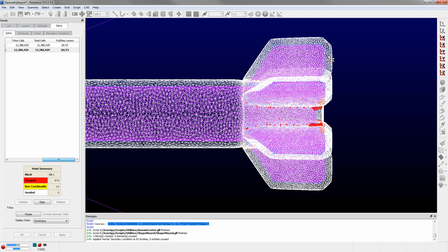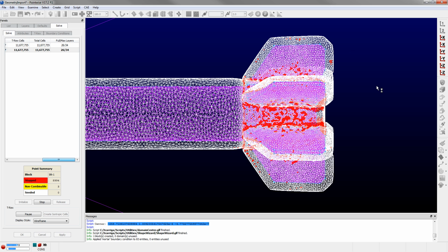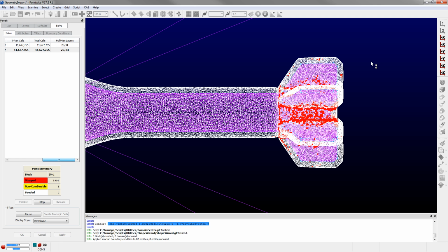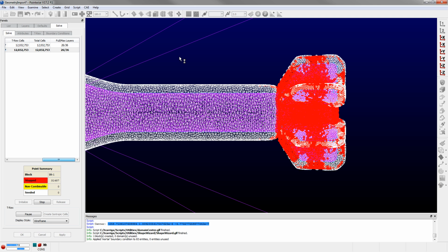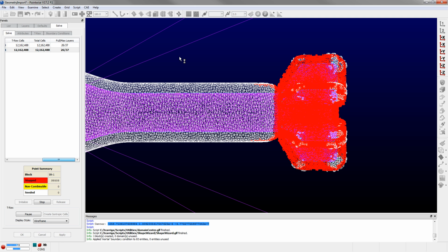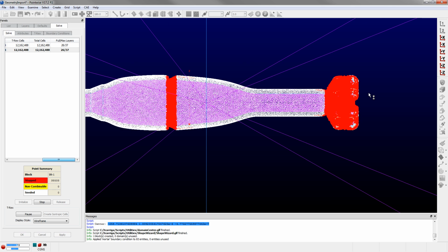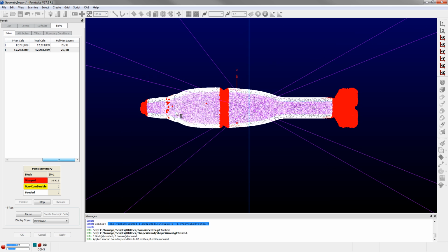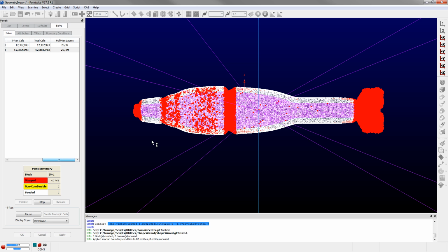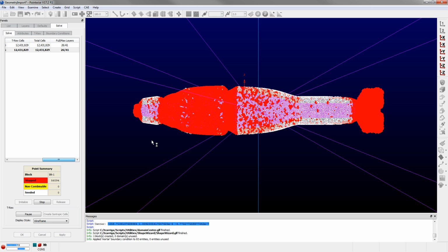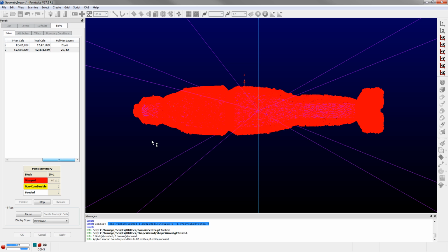So you can see how thick this boundary layer region is. It's really nice. And just because points are stopping locally doesn't mean the entire front has to stop. That's the real benefit over a traditional prism inflation, we can continue advancing everywhere else where there's no problem, where it hasn't reached an isotropic ideal state. Eventually you want the entire front to turn red. That basically means you've achieved an ideal state, and we can then take that and transition to the isotropic TET far field.